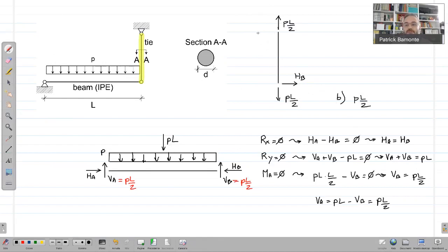What about the rotation equilibrium? Now, having mentioned the fact that since this is a truss, okay, there are no other forces than the axial force, I could immediately delete HB, but let's see why HB is 0, just to brush up a little bit on basic concepts we mentioned during the classes. So if you have HB at the bottom, you should have HB at the top in order to guarantee translation equilibrium in the horizontal direction.